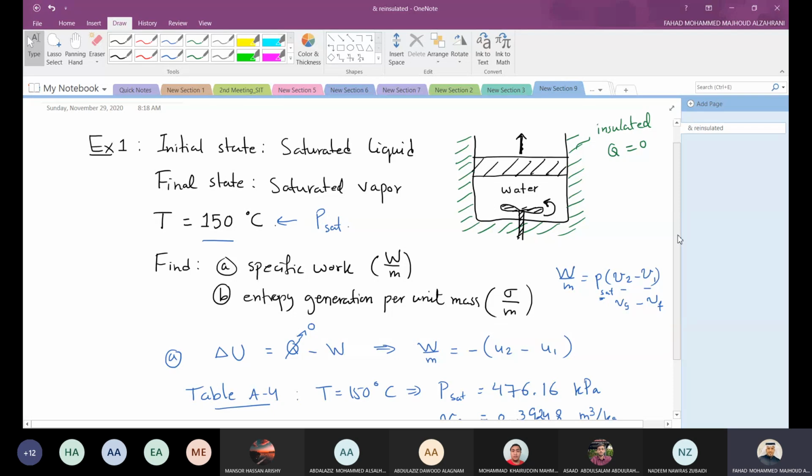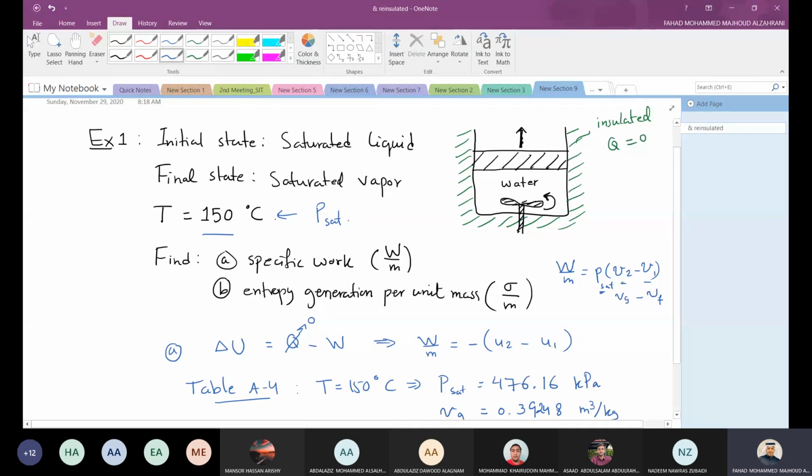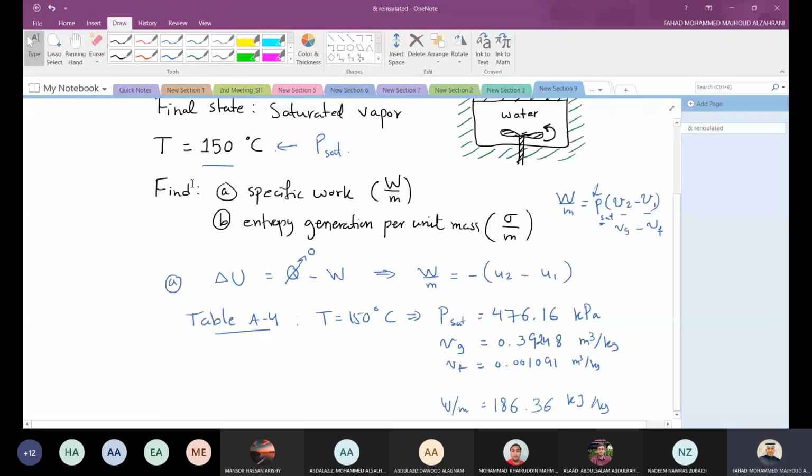The reason for this is that the pressure here is not the right pressure; the pressure inside will change. That's what I believe is happening. Because of that, I cannot use this equation. So this is the wrong way to do it. If you have 100% expansion or compression without any other factors, you are right. But I have a fan here, so I cannot use PdV. I have to use the energy balance. It is way off.